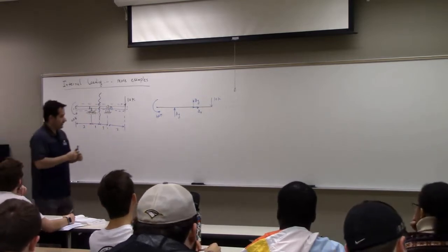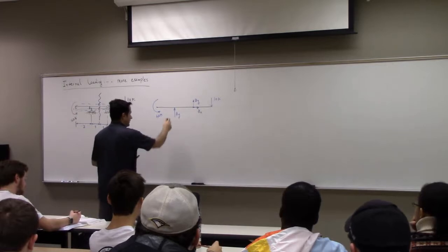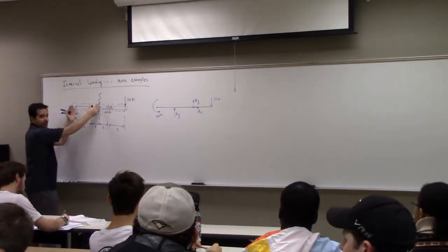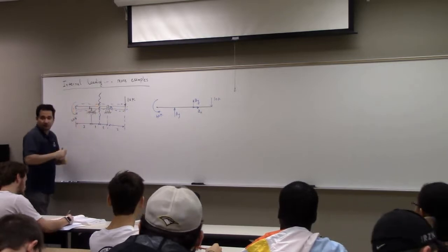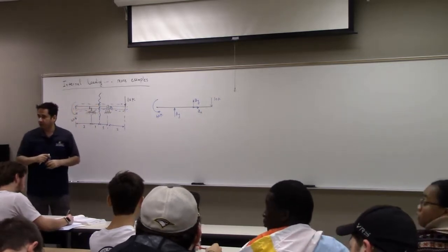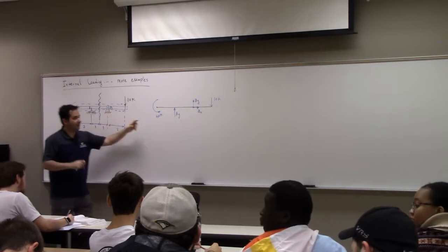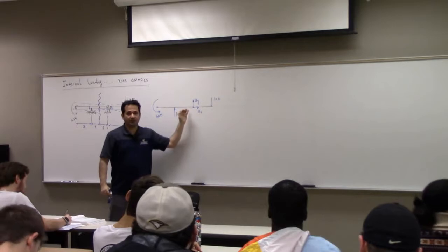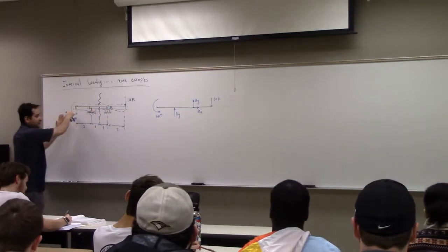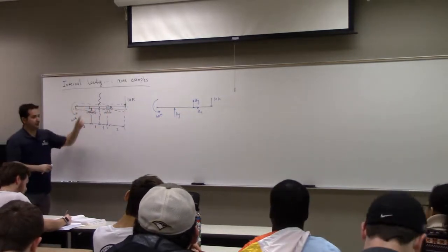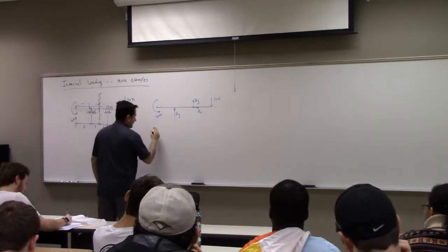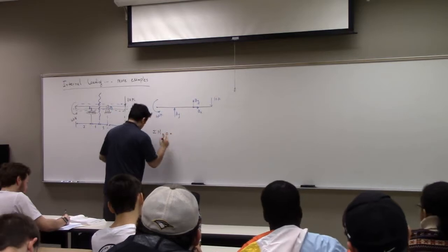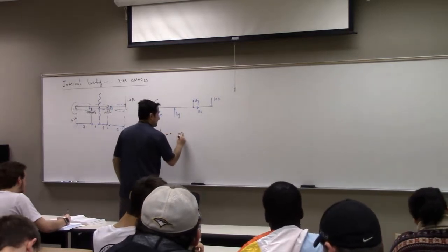So now I want to find Ay only. Why? Because my plan is I take the one on the left, right? So you can save up your time without going to both Bx, By, because I can just find the reaction at point C with just taking everything on the left. So I just want Ay. So in order to get Ay, I write one moment equation at what point? B.